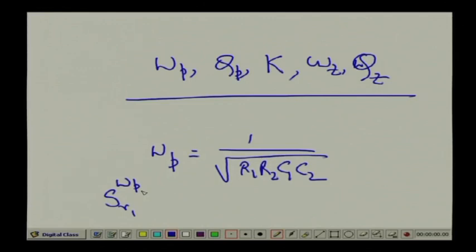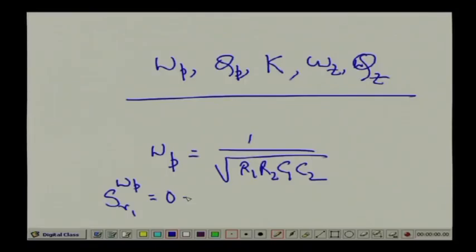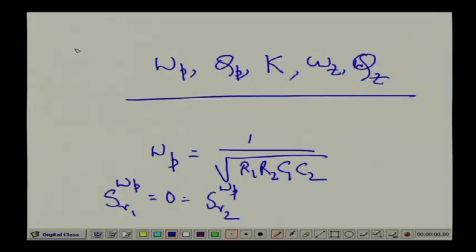That is also there in the case of positive feedback topology. Since it is not there, if I vary small r 1, how much will our pole frequency change? Nothing, is it not, right. So, it is obviously 0, and similarly for S omega p small r 2. Clear? This is our sensitivities figure, right.